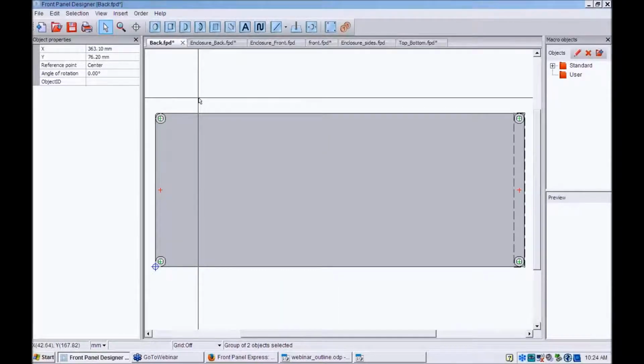Is there an option to use threaded inserts in place of self-tapping screws? This is an extrusion that only is not a complete hole. We can set them up as customer material and mill them. If you would like to place an insert yourself, you may. On the housing profiles, we actually thread the material and use machine screws. So just the side profiles alone use the self-tapping screws.